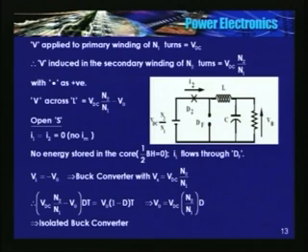What is the current just prior to opening the switch in the primary? There is no magnetizing current, because we have assumed the core to be ideal, or mu r is infinity, reluctance is 0, magnetizing current is 0. So primary current is equal to the secondary current, I1 is equal to I2 prime. So when I open the switch, I1 becomes 0.